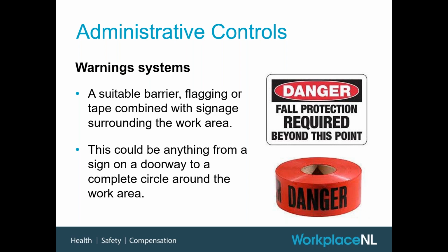Really, they were using a guardrail as a warning system, which is confusing, because in most cases, when you see a guardrail, you expect it to handle you leaning on it. If it was truly just to warn, they should have had that system back a distance from the edge, so that if someone did lean on it, they wouldn't be able to fall.